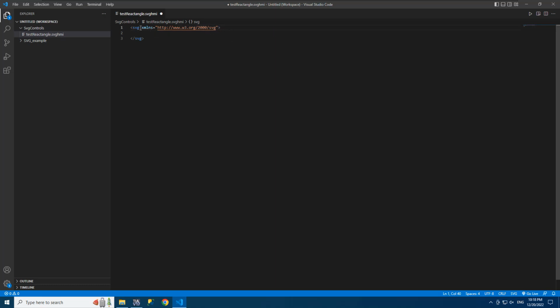As you can see here, we have this attribute xmlns. I want to go into detail about this because it's an important point. For WinCC Unified widgets, we need to connect at least two namespaces. What is a namespace? A namespace is a special prefix defined by the XML standard. It is needed to extend the functionality and possibilities of XML. SVG is a special case of the XML standard, with its syntax of opening and closing tags and attributes.